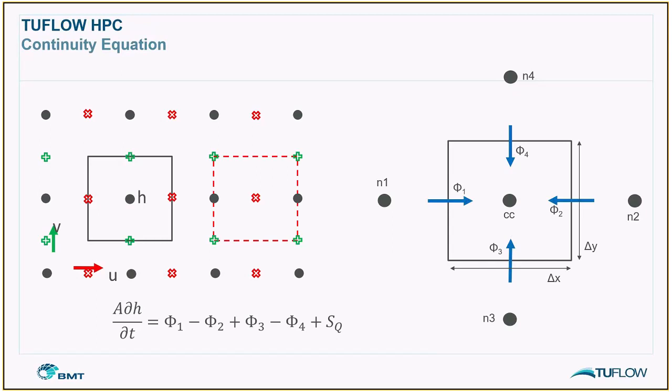The computed derivatives for H, U, and V are local in time and may be computed for each cell independently of other cells. That means that the calculation steps are highly independent and can be distributed across multiple CPU and also onto GPU cards.